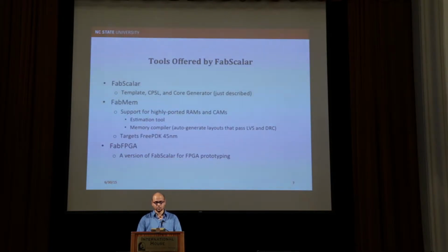It supports highly ported RAMs and CAMs, which are pretty pervasive in any out-of-order superscalar design. It has an estimation tool that does some sort of design space exploration before coming up with the optimum array layout. And it'll also generate actual physical layouts that are LVS and DRC clean for the FreePDK 45 process.